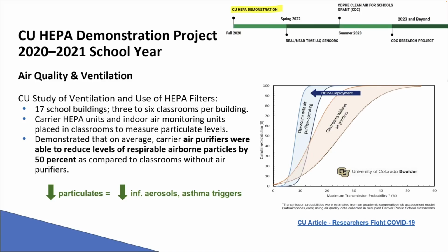Initially, 25 schools were selected, and then since only elementary level kids were being brought back to the buildings after COVID, the focus shifted to elementary buildings. Classroom testing of air changes with the CO2 decay method eliminated some additional schools and classrooms as we found that they had adequate or good air exchange rates.